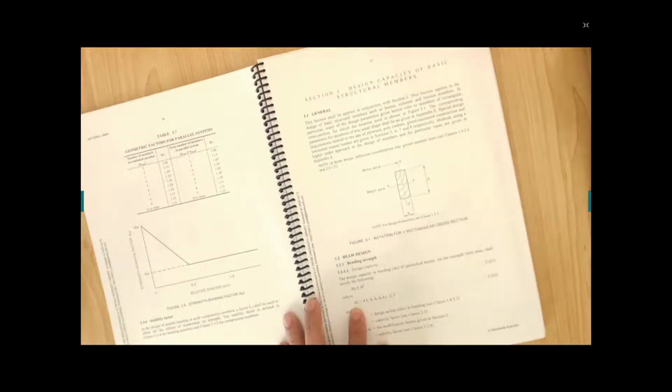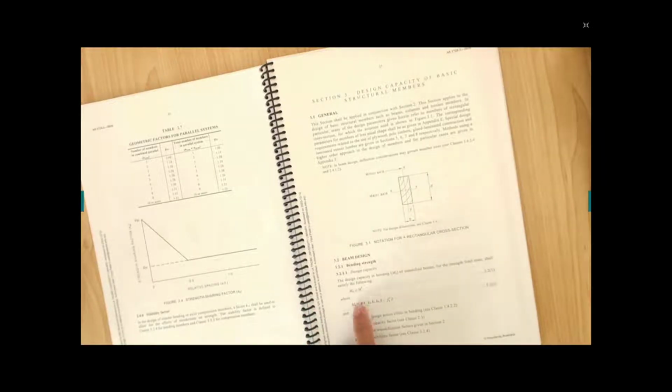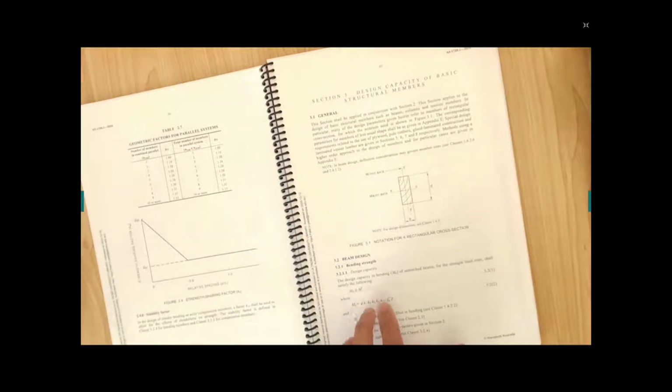MD, the symbol MD, represents the bending capacity of your timber beam, which has a capacity reduction factor. As you know, this is in steel as well. We have 5 factors. There are K values that I'm going to take you through in the lectures, and there is a bending strength, bending stress, and a section modulus value that I'm going to introduce to you as well.